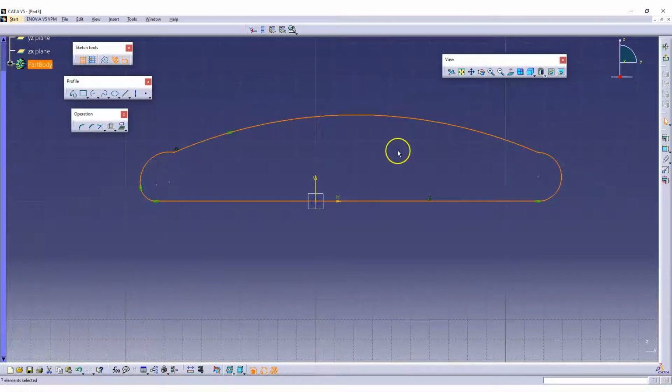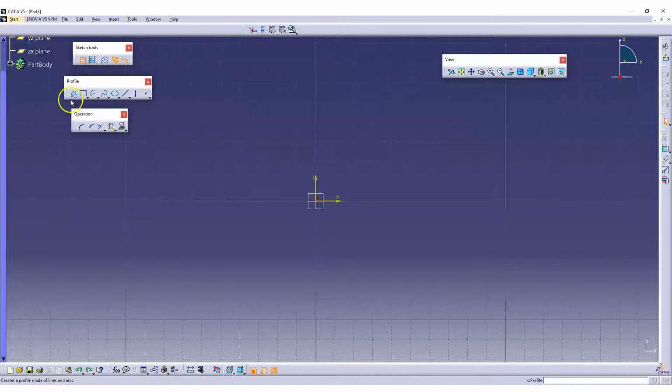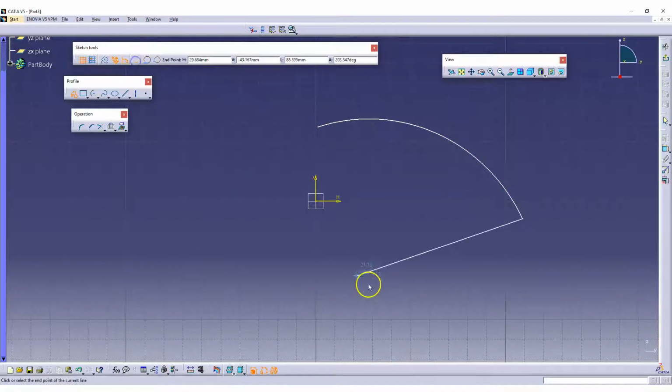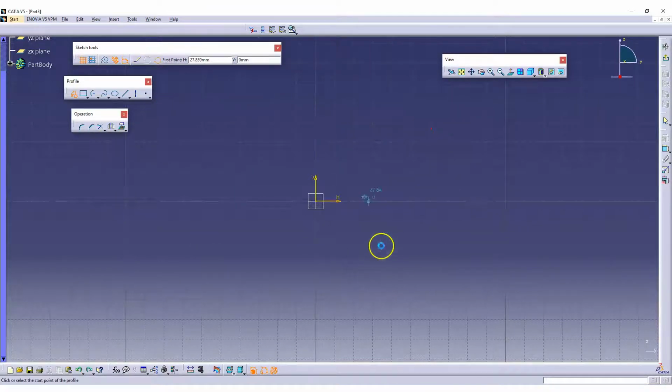So that means you can create your profile using 3 options. The moment you click on this one, you can see the sketch tool expands, and you can see tangent arc, 3-point arc. Default line will be active, and if you want to start with a 3-point arc, you can just draw this one. This is my 3-point arc, which I can use. If you want to start with a line, you can just start. But at the start, you can't use a tangent arc. Tangent needs either an arc or a line. So starting itself, you can't do that. So that is your profile.